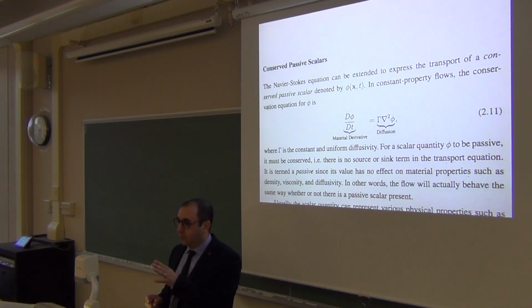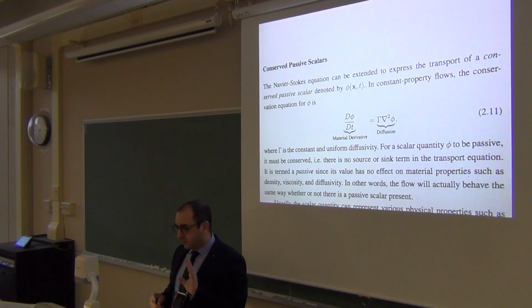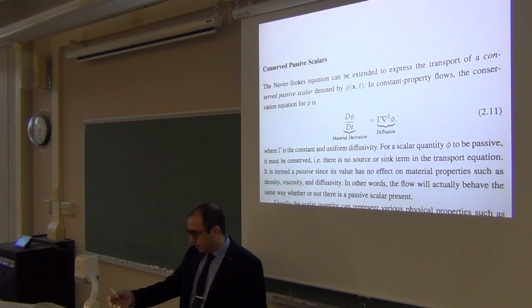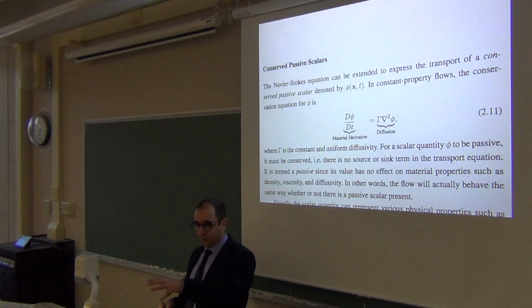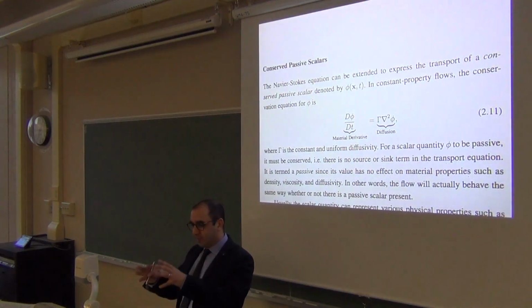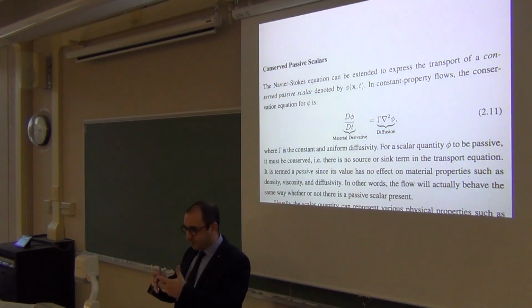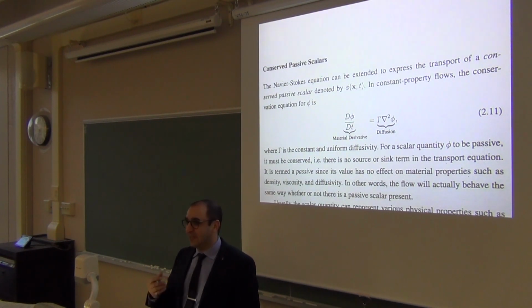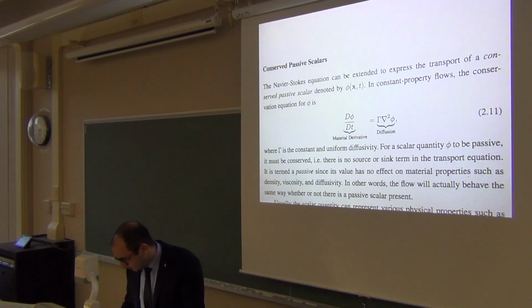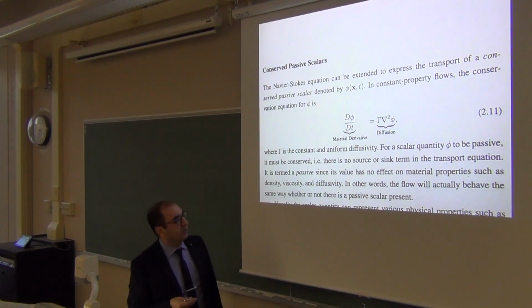Although that's not true for all other transport equations. Other things can happen. If you solve for the energy equation, that is a two-way relationship, right? If I have, like this light here generates some heat, and there's a thermal plume, right? So a source of heat causes air motion in a certain way. It's tightly coupled with momentum. So we don't call that a passive energy equation. There's no such thing. It's the coupled energy equation. So it's a very important concept.